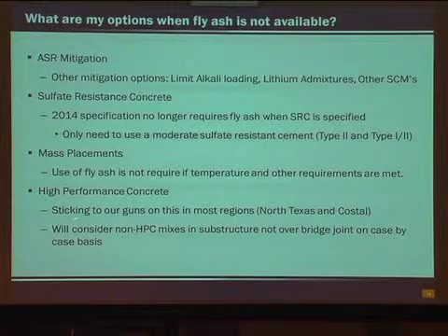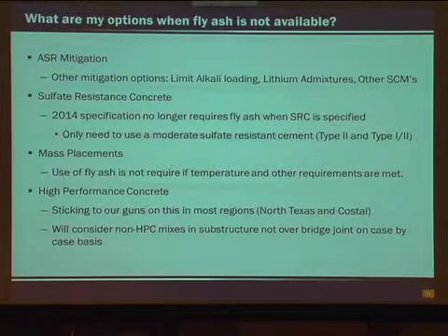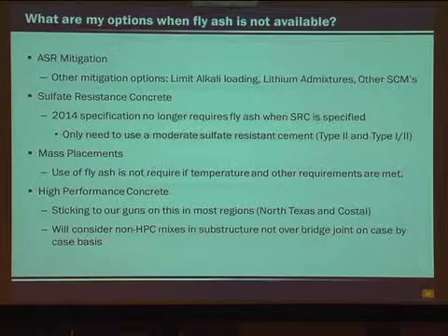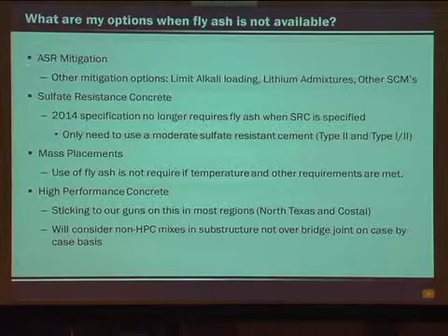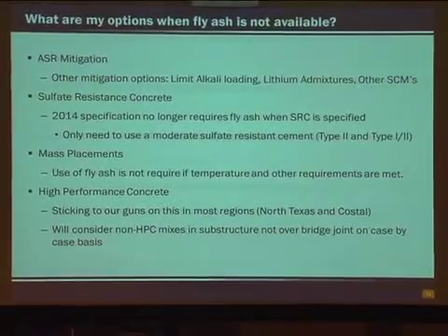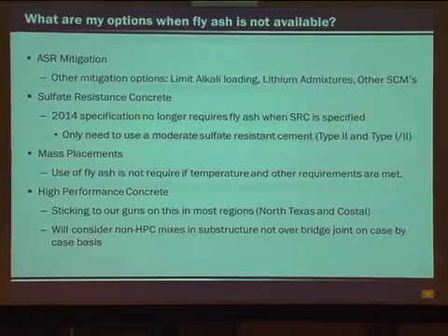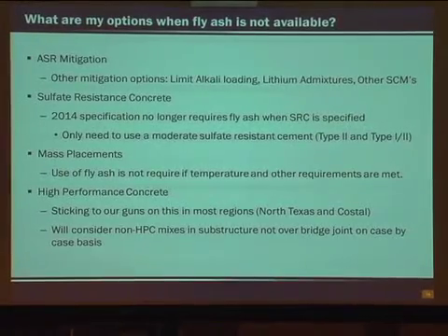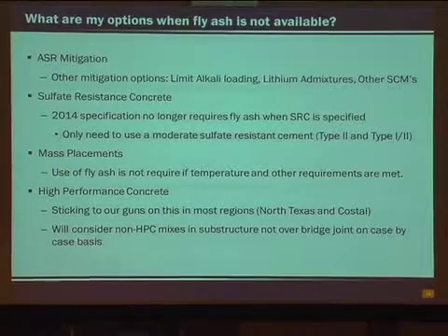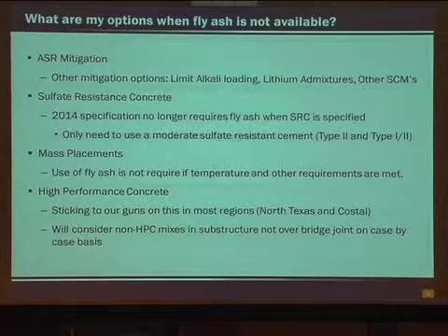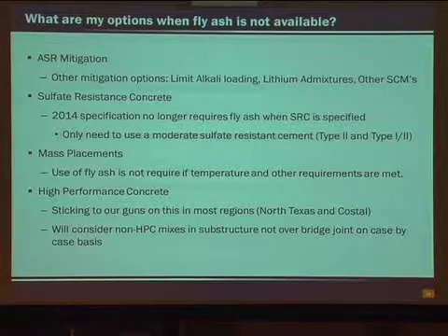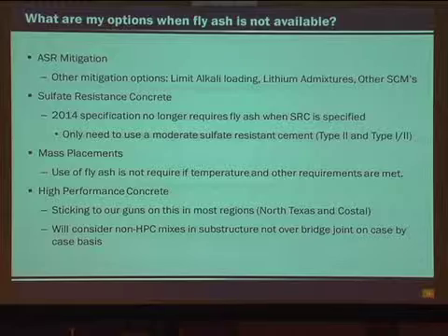High performance concrete, however, I think with talking to Bridge, we're sticking to our guns. This is where we want fly ash. We don't want to really bend on this one. However, Bridge will consider some situations where substructures that aren't over joints can use non-HPC, but that's on a case-by-case basis. You'll have to talk to the Bridge guys on if they want to really go that way.